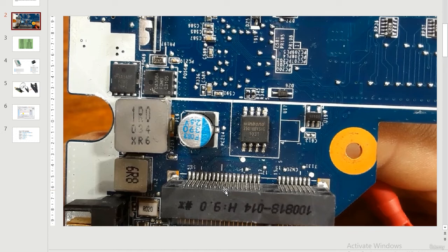So if you check all these accessories and all these parts, you check the memory, especially the random access memory. If you check the random access memory, you find it connected correctly to the RAM slot. You check all connectors, you check the hard disk drive, the ODD or the optical disk drive, and you find all these are installed correctly, but the beeps still persist, which means you should reprogram the BIOS. The BIOS file is probably corrupted.